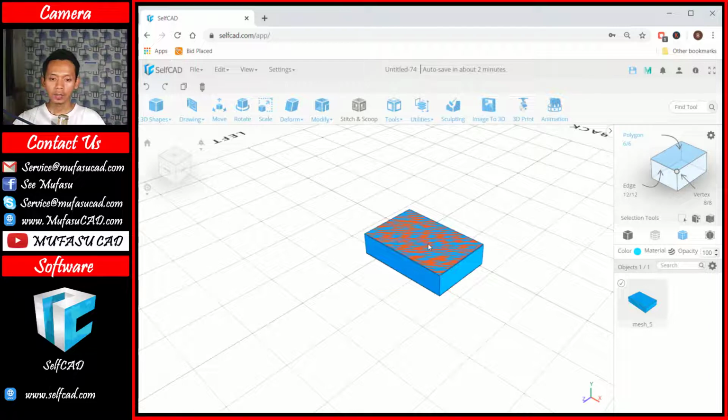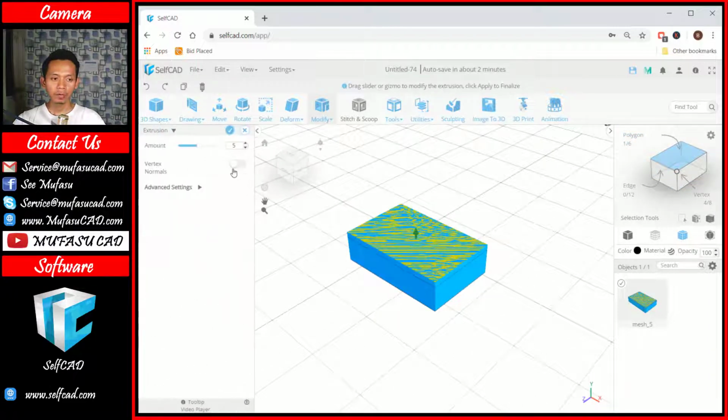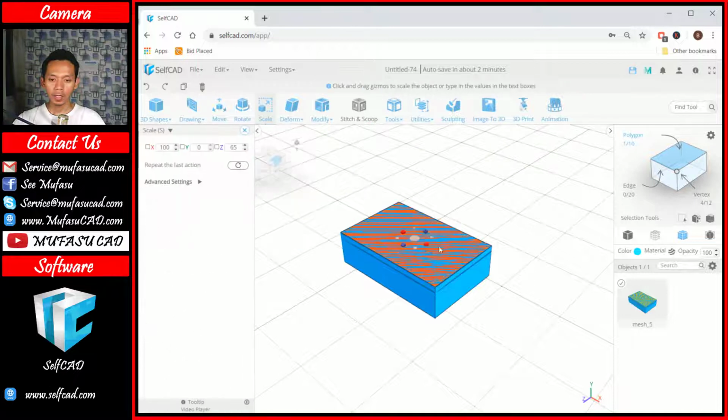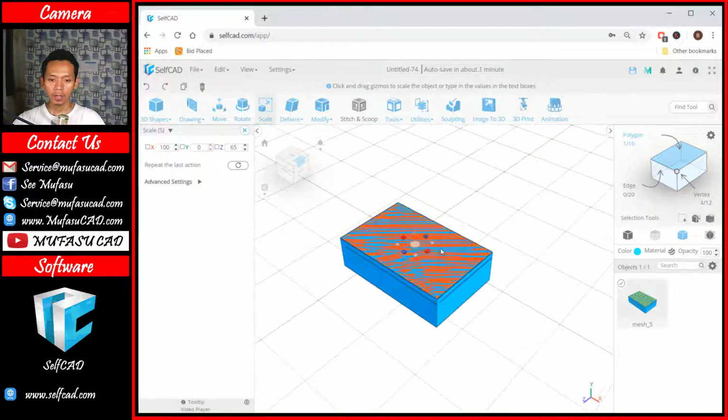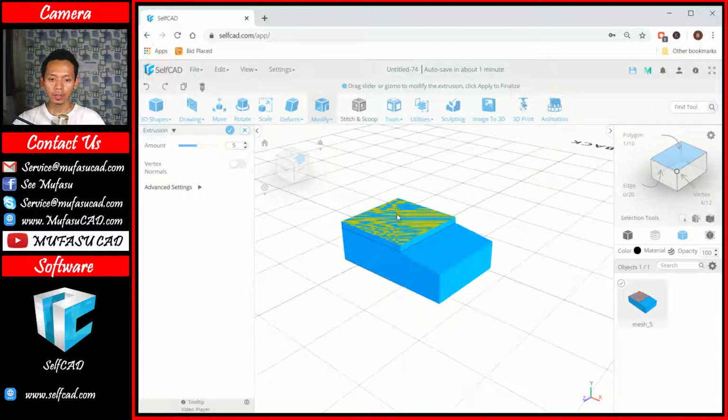You can click at this face, and next I will use extrusion. Okay, we extrude in an amount of 5. Next I will use the scale command. We can scale in the right axis. Okay, you can click in here, right axis into here, and the last we can use extrusion again. I will extrude this face to the top, to this point.